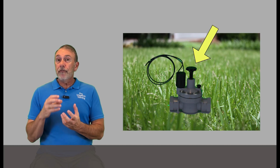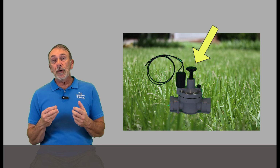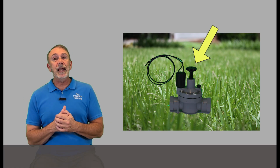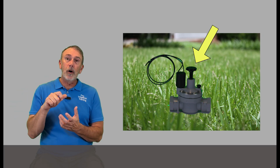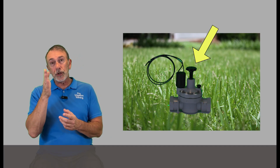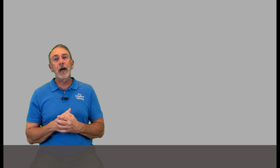But there are things that we can do, right? There are valves that have flow control knobs on the top. If you're experiencing some water hammer in your irrigation system, and this isn't your fault or whatever, and you can't remove heads to bring that flow amount back down, you can go to the valve and start to crank down the flow control on it. Of course, you run the zone and then you go to the valve and you watch it and you crank that flow control down until the point it starts to affect your performance. What happens is the spring and the diaphragm will stop that to a certain extent. If it's really bad, it may not stop it.